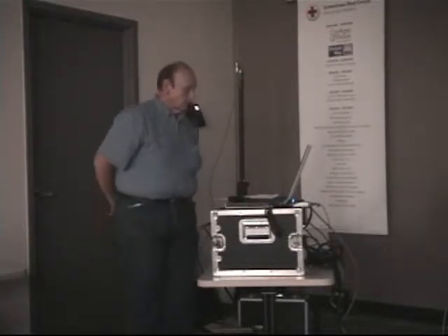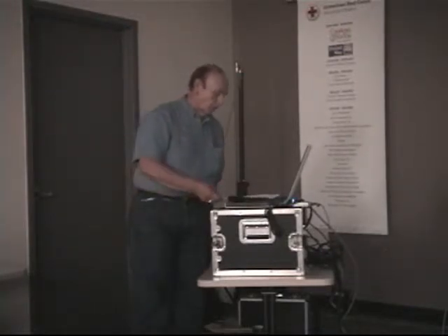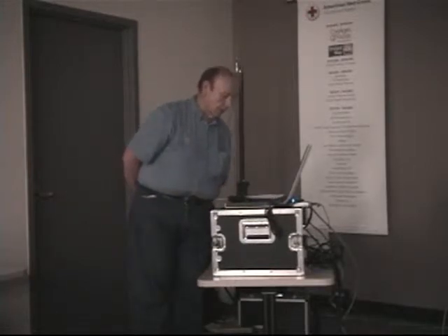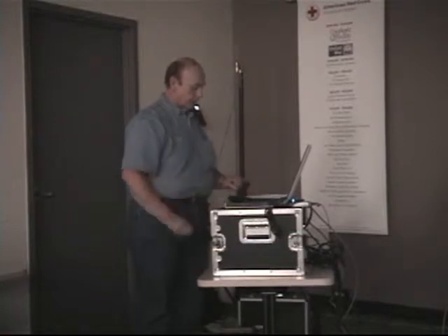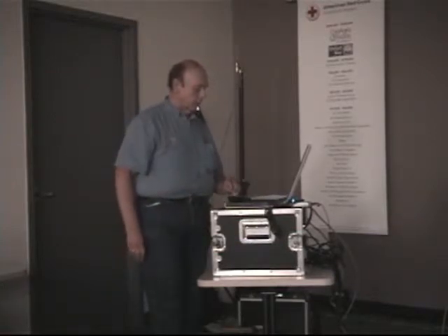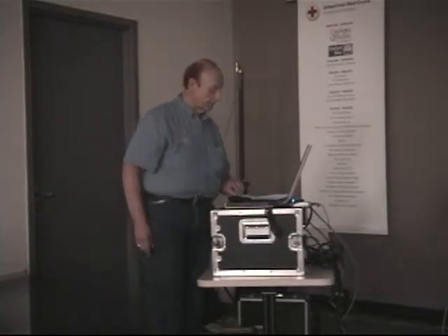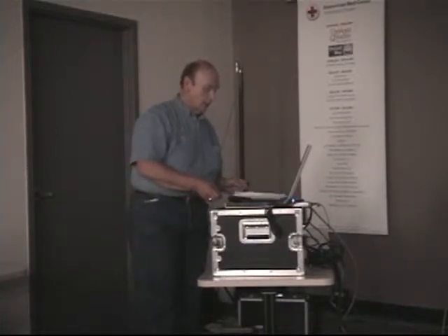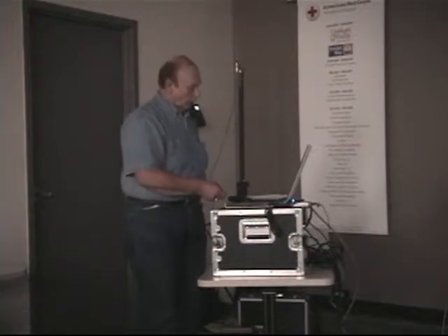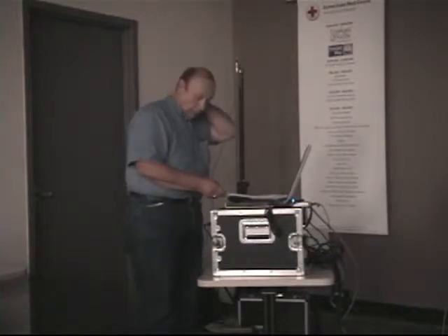Why DMR? Well, it has superior RF performance. In high-speed digital mobile communications, transmission performance is severely degraded by frequency selective fading caused by the time delay spread of multipath propagation, which we have the demonstration. The DMR digital receiver provides better noise rejection and preserves voice quality over a greater range than analog, specifically in the farthest edges of the transmission range.